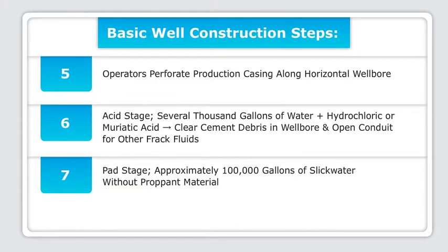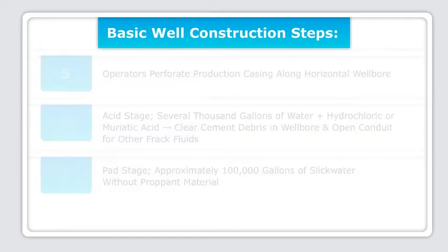7. Pad stage, consisting of approximately 100,000 gallons of slick water without proppant material. The slickwater pad stage fills the wellbore with the slickwater solution, opens the formation, and helps to facilitate the flow and placement of proppant material.